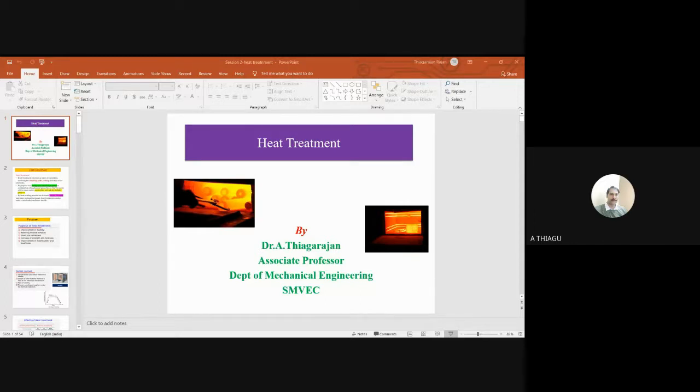The inside or core should be soft and the outer should be hard, because we modify the outer surface by means of diffusion or depositing of carbon and nitrogen. So ultimately we can improve the mechanical properties, and hardness will be increased.